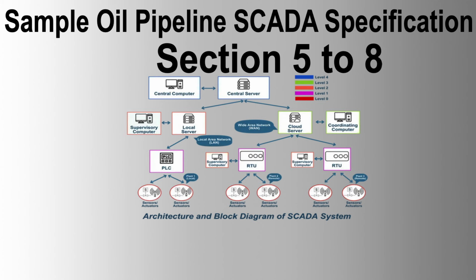6.5 Identification. Each equipment item shall be identified by its unique project number via legend plate mounted on the front exterior face of the cabinet. Legend plates shall be manufactured from grade 316 stainless steel, deeply engraved and filled black. Legend characters shall be boldly engraved and 15 mm high.